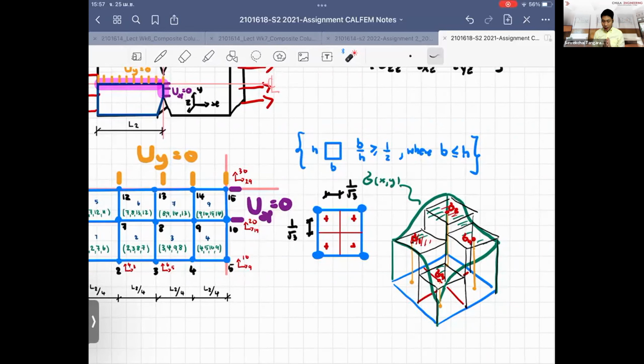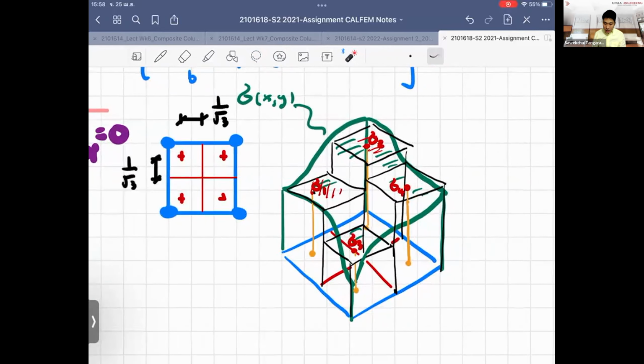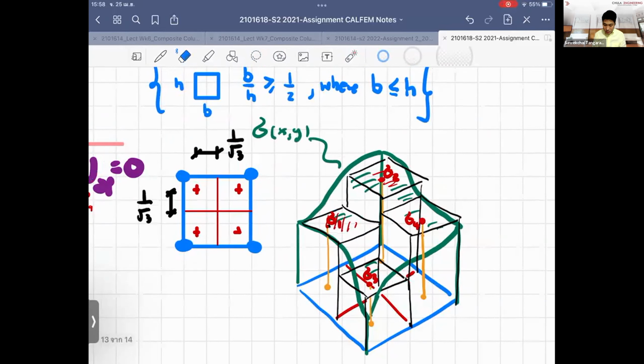So that's why in the area of finite element, people try to develop the robust element. A robust element doesn't need much information. You can approximate the value of the stresses by using the Gauss points, so you just approximate them as a linear surface, but we want the nonlinear hypersurface. This is the nonlinear hypersurface, but we use a linear surface to approximate it, right? Then the values at the Gauss points normally return you a set, right?